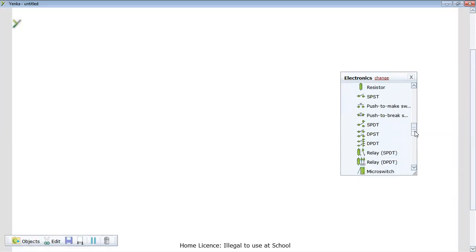Now, in today's one, we were looking at the pneumatic circuits, most importantly, the difference between an AND circuit and an OR circuit. And this is your opportunity now to model them. Now, the biggest thing to remember is the difference between the two of them. The main characteristic is the AND circuit consists of those two valves, those two switches. They both need to be connected, turned on for the circuit to work, and then for it to activate the cylinder in this case,